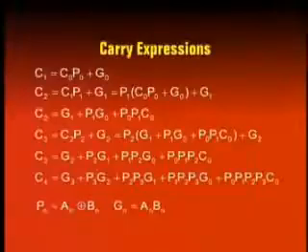Carry 1 output is based on the carry input to the first full adder, the carry propagate term and the carry generate term. So C1 is equal to the product between C0 and P0 plus G0. Similarly, carry 2 is represented by the expression C1 ANDed with P1 plus G1. C1 can be represented by the expression C0 P0 plus G0. So the expression for carry 2 simplifies to G1 plus P1 G0 plus P0 P1 C0.